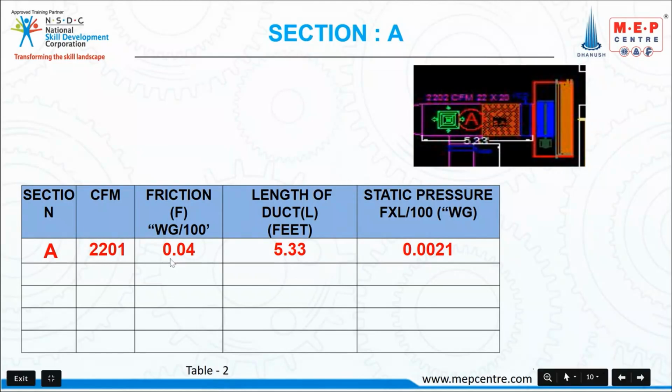Open the duct size tool. So 2201 CFM. Okay, I have opened the tools. 2202. Okay, next, not head loss, put 800 in the velocity. Okay, 0.04. Yeah, so that is the friction value, head loss value you calculate and you put it constant throughout the ducting, right? Yes. Equal friction method. Yeah. So that value I am taking here.